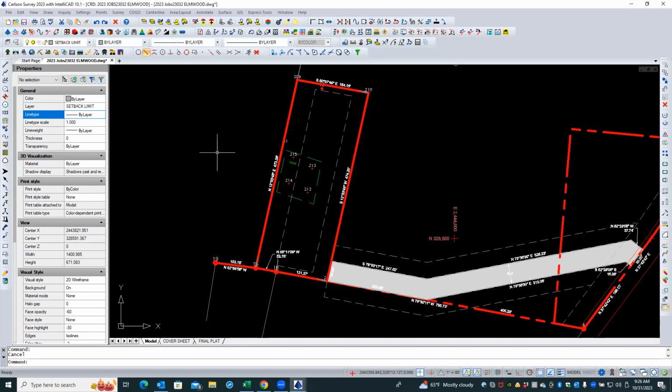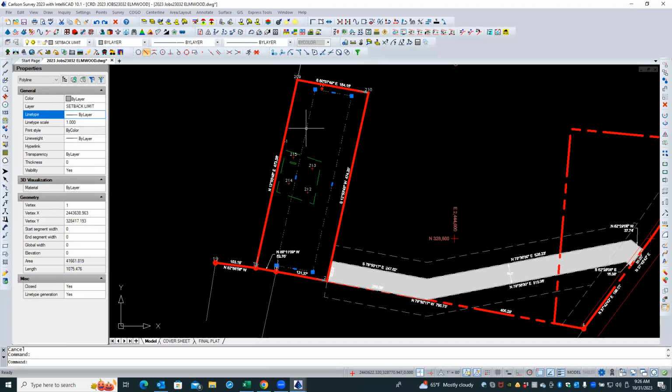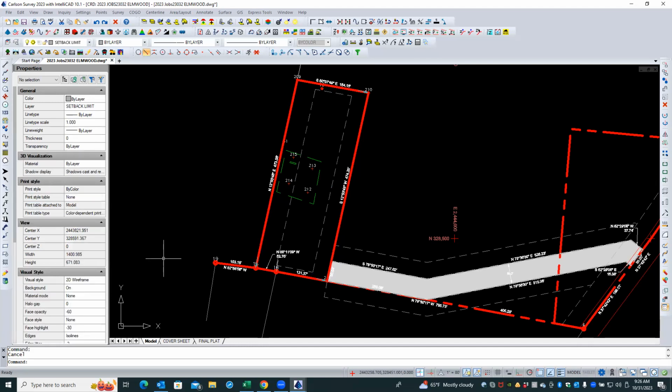Now I would also, since that is corner to corner, select that line, and you see the northeast corner, how there's a gap at the corner. If you do that and go to your properties, the very bottom one, the line type generation, if you turn that off, that will start it over. Let's see how that looks. Now escape that, and you can see you've got the full corners. Okay. All right. And that same thing with that dashed green in the middle. You can see the corners are gapped on that one as well. The ones around 212 through 215 in that area.